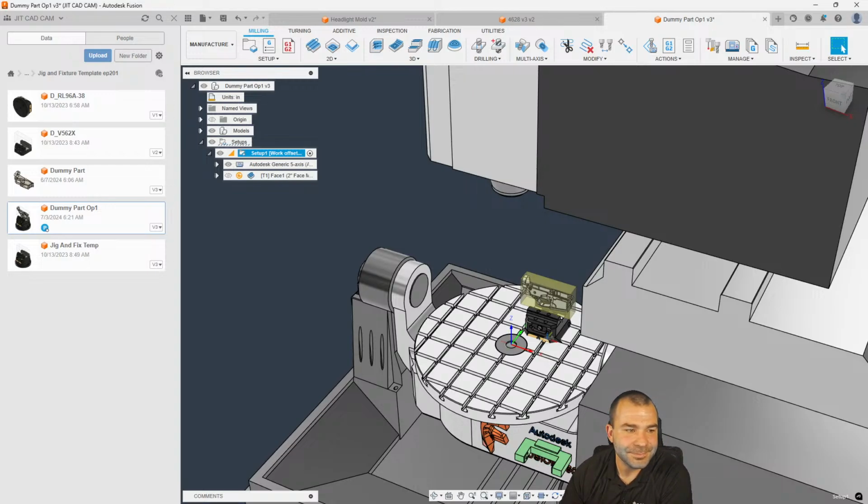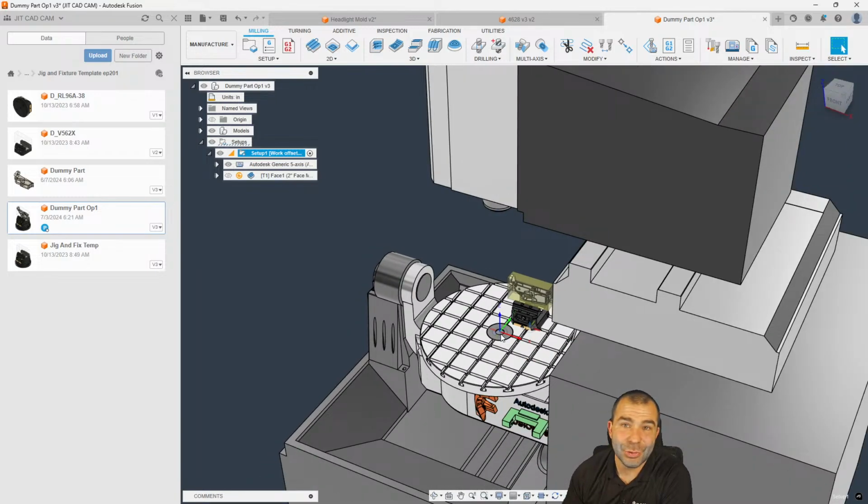Let's go. So again, we use that joint origin to define where our center of rotation is. I always tell people when you find your center of rotation, you make that G59 at your controller, and then usually you never use G59, because if you're going to use 54 to 58, that's 4 offsets. If I need more than 4 offsets, I usually go to my P values, right? G154 P1 through 1000, right? But once you put that in and you know where that location is, until you take your rotary out and put your rotary back, it makes no difference because it's always going to be that same location.